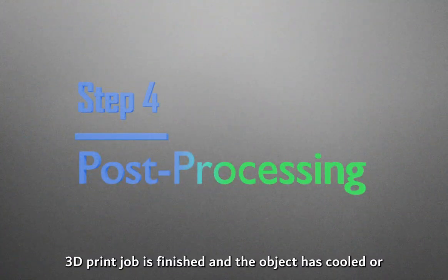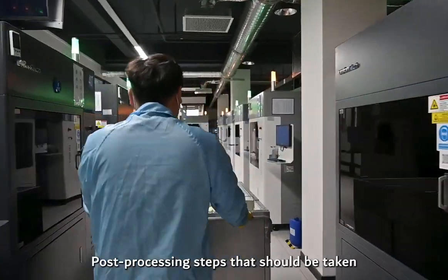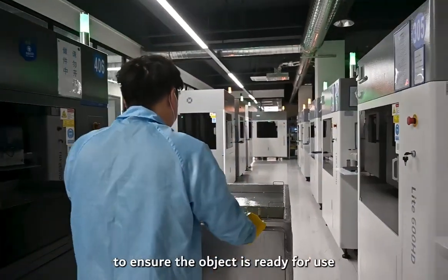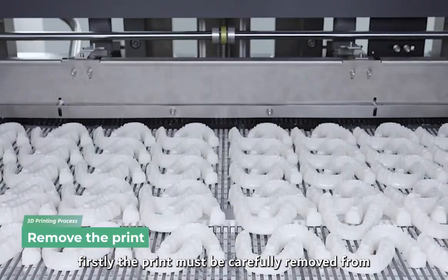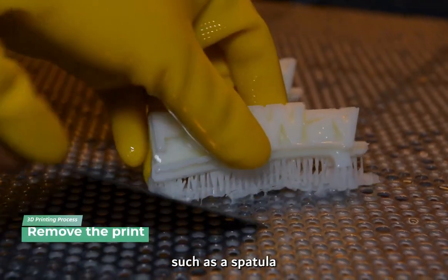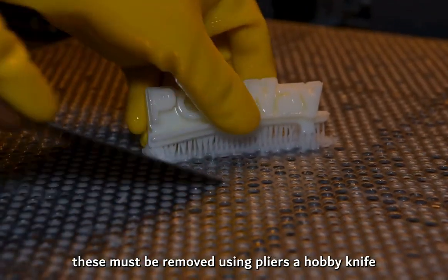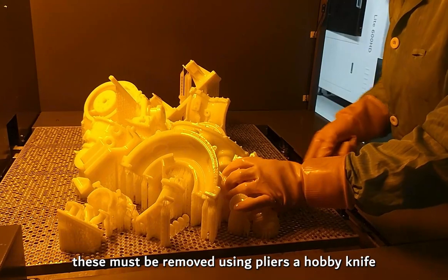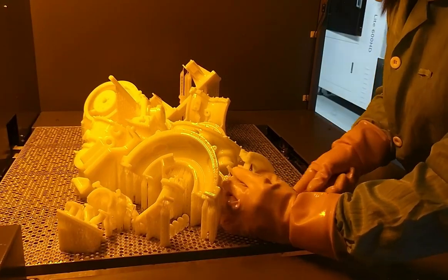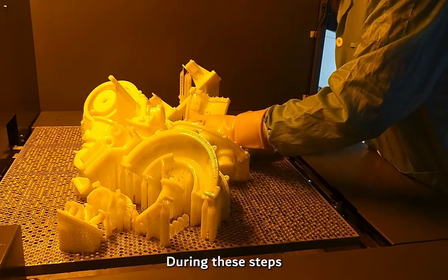4. Post-processing. After a 3D print job is finished and the object has cooled or cured, there are several post-processing steps that should be taken to ensure the object is ready for use. Firstly, the print must be carefully removed from the build platform using an appropriate tool, such as a spatula. If the model required supports, these must be removed using pliers, a hobby knife, or other suitable tools. It is important to be cautious not to damage the object during these steps.